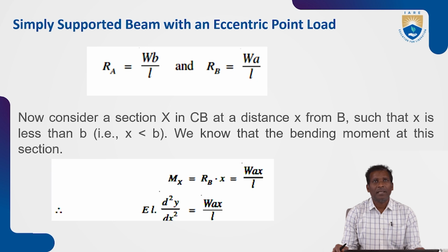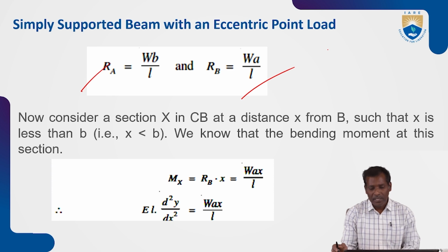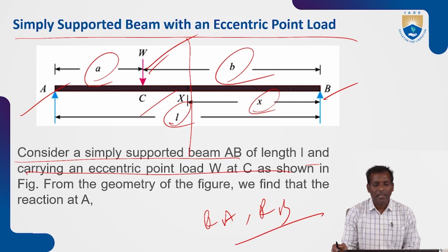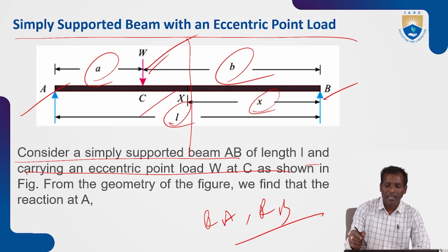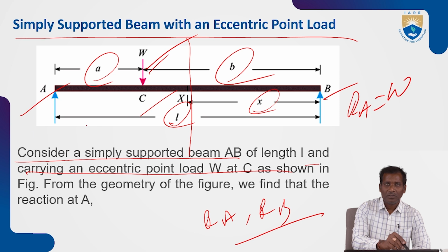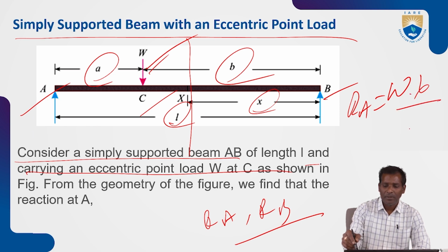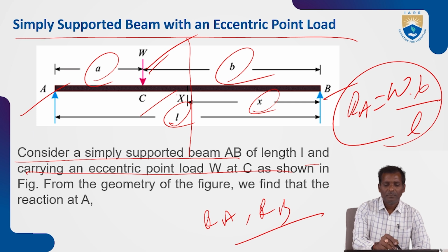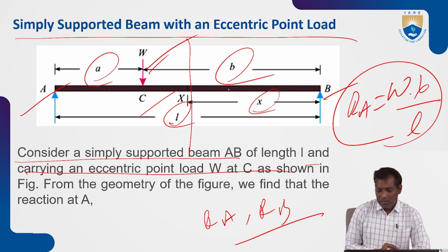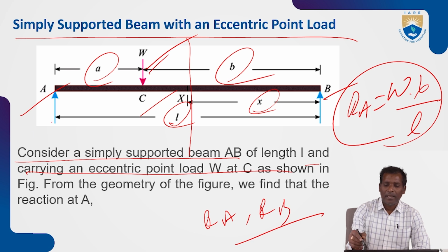The reaction force at A, RA, is W b by L. Taking moments about B, RA is W into b by L. Similarly, RB is W into a by L.